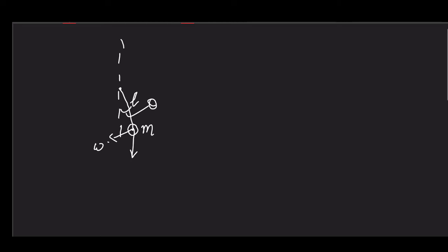If you consider an RLC series circuit, obviously R cannot store energy, only L and C can. We know we can have an infinite number of state models for a single system, but if we want a physical model, we take inductor current and capacitor voltage, because these are the two variables associated with energy storage, right? So that is the case.